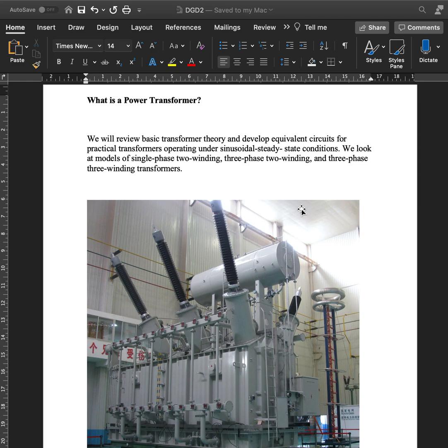This is useful to do, because as you know, current is directly proportional to the loss, right? The heat loss. So that is I square R. Hence, when we have a high voltage, then the current will be low. So during the transmission line, there is less loss during the transmission, basically.